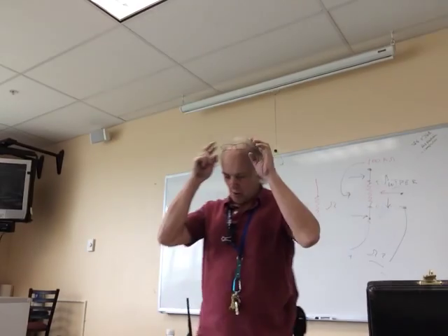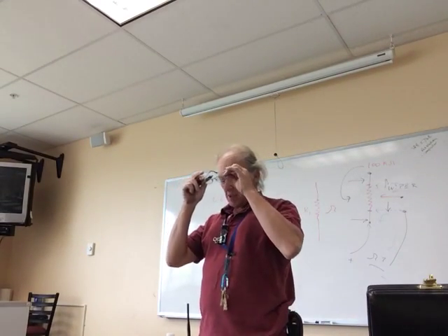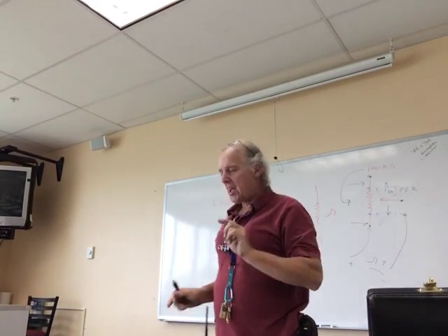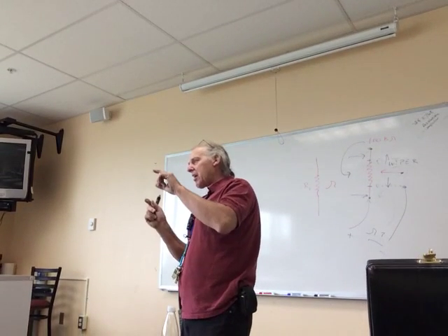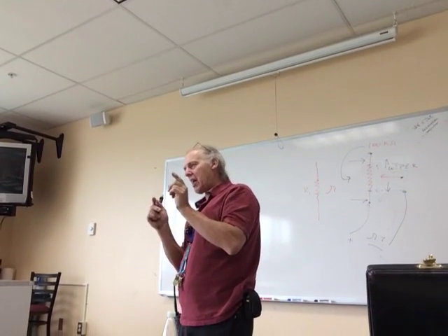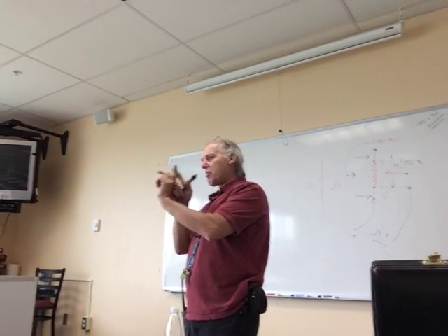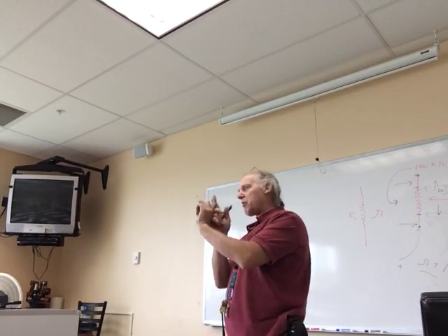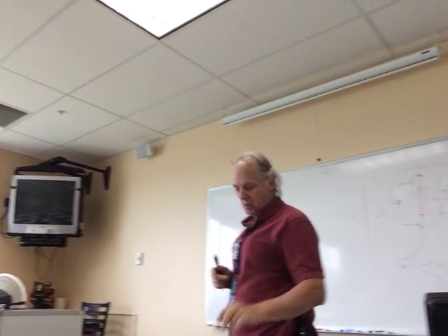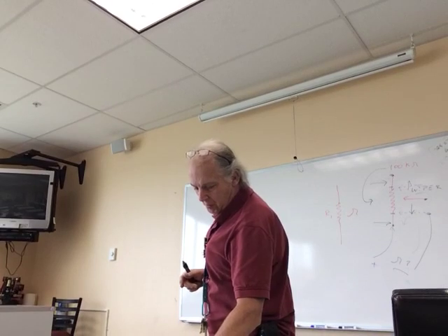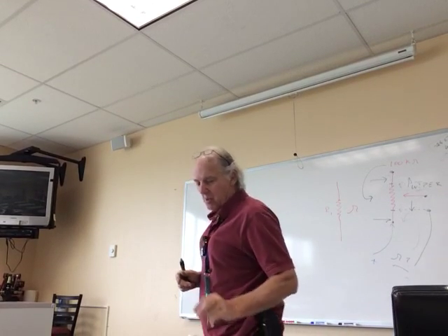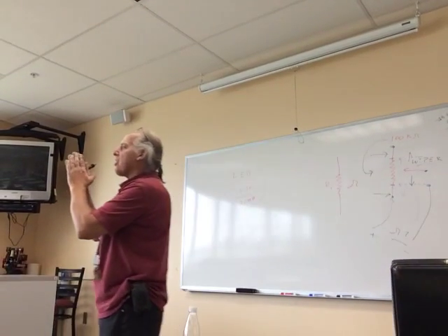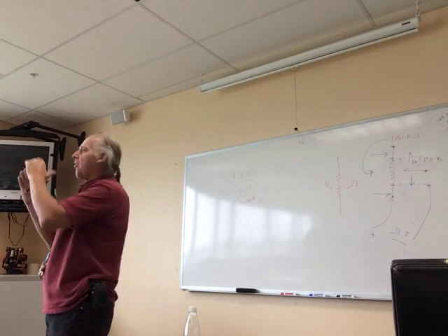It's a balanced circuit. We put a voltmeter in the center. When we change one of the resistors, we either get current flow one direction or the other. The meter is going to have a zero position. It can go negative or positive. And you can see in the picture, we put the voltmeter right in the center. So what's going to happen is we're going to see current flowing in one direction or the other direction.